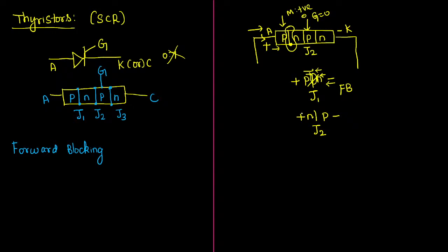Now what will happen? See there, positive charge will be attracting negative charges. This negative supply will be attracting positive charges. Then what happens? Depletion layer width will keep on increasing. All the charges go outside, and there will be no conduction inside. This is called reverse bias.